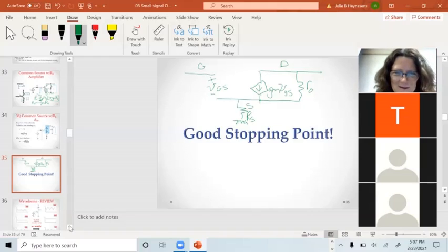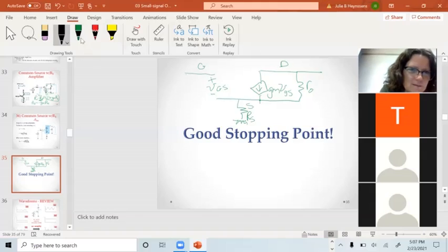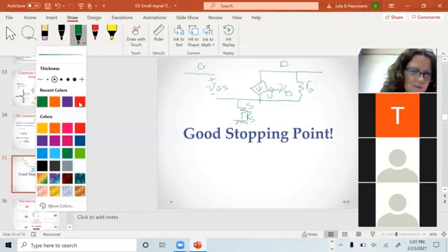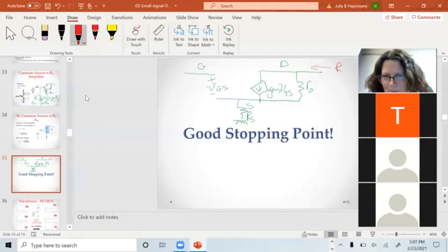I just realized how bad this is. What we're going to do is follow the rules of Thevenin, and I'll explain why you want to use the diagram. Following the rules of Thevenin, if we want to find the output resistance looking into there, I would ground the gate. The source is already grounded through the source resistance, and I deactivate any independent sources.